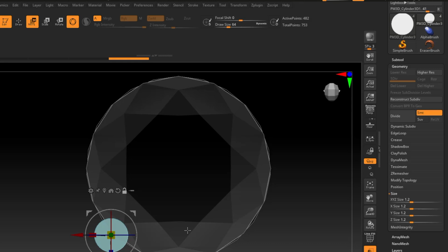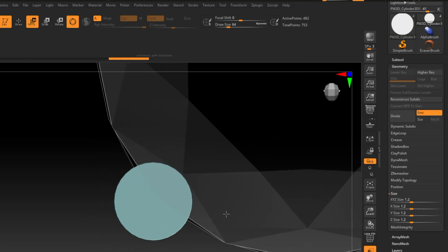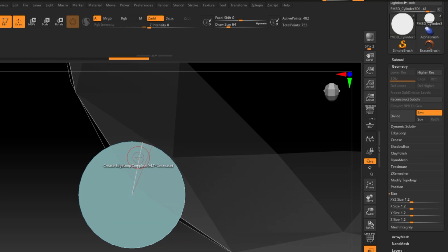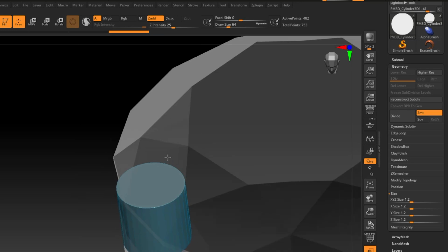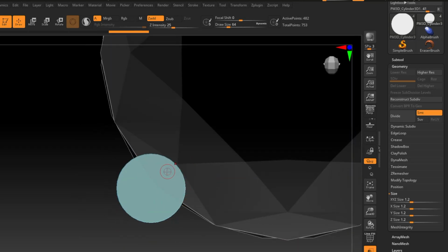When you're placing your prongs, you do want a bit of overlap. So let me zoom in, and I'll turn off the gizmo so you can see a little bit better. So you can see the line of the stone right here. Now my cursor, this little point, is snapping to about the center point. Now when you're setting a stone, you typically want the stone to not go any further than 50% into the prong. And the reason for that is this area out here where this metal is, that's what's going to be subjected to the elements. So things like rubbing up against tables or bumping into something, this is the area that's going to get the most wear and tear.